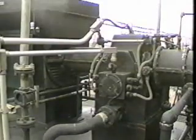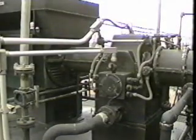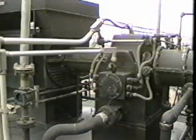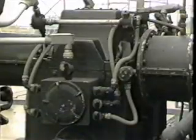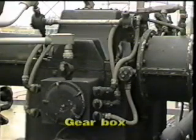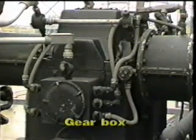In compressors driven by electric motors, speed is generally limited to around 3,600 RPM. In these cases, the electric motor may be coupled directly to a low-speed centrifugal compressor. To operate the centrifugal compressor at higher speeds, the motor must be coupled through a speed-increasing gearbox. This is known as a gear drive.